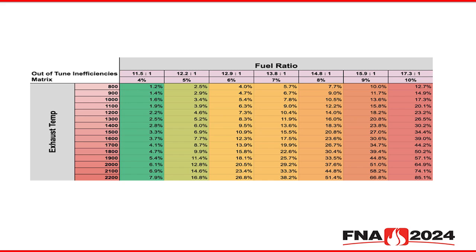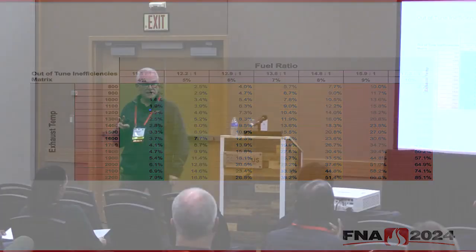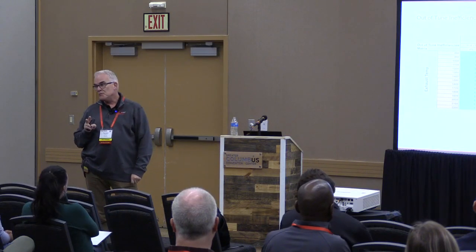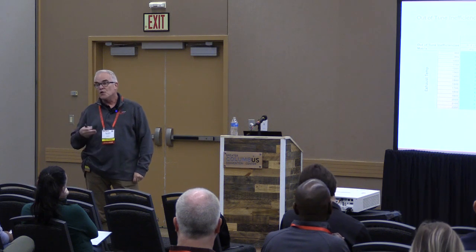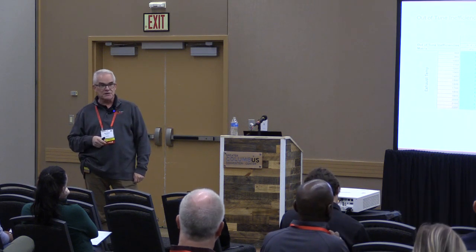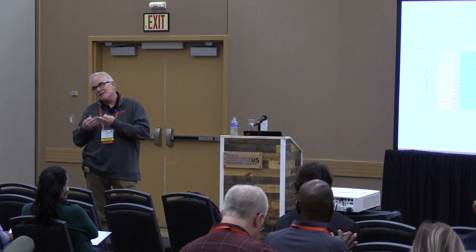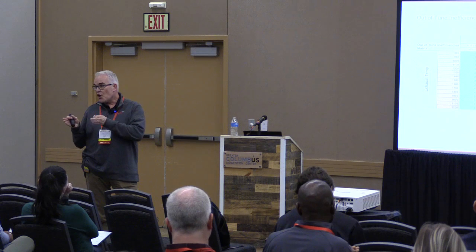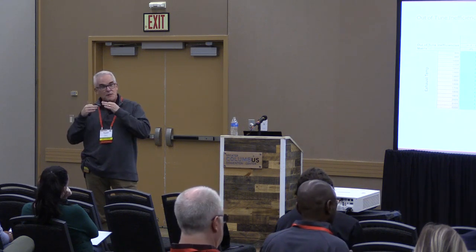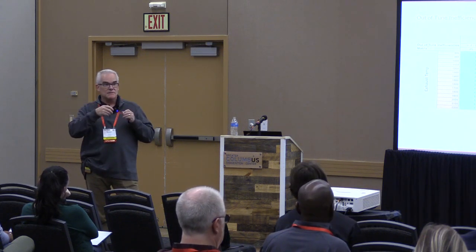And again, that cuts 2 ways. 1, you're buying gas you don't need. And 2, because you're burning more gas than you need, you're making more CO2 than you would if the burner was properly tuned. So when you start looking at why it is important to maintain proper combustion in a furnace, there's certainly a cost element, and depending on how much the gas is,